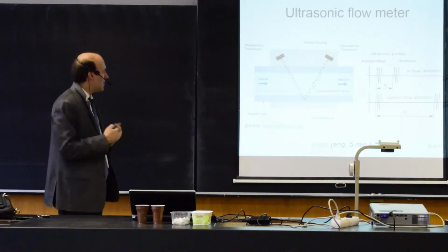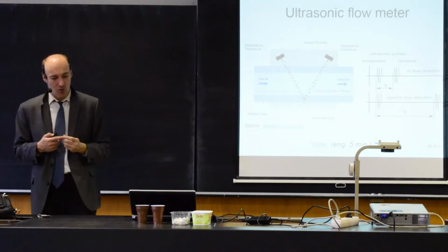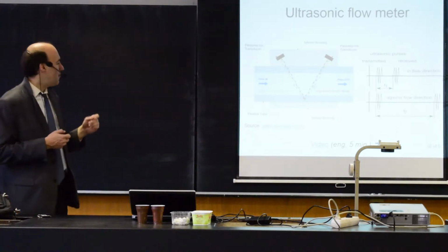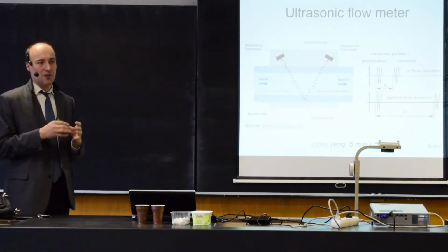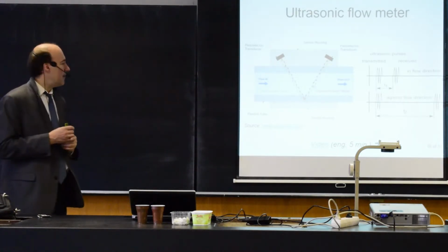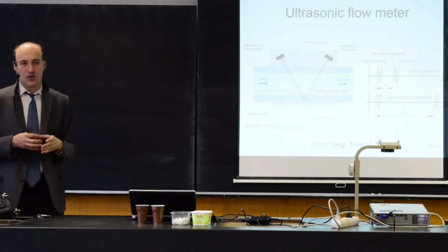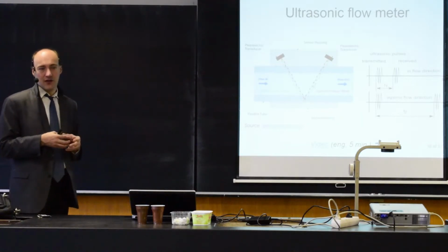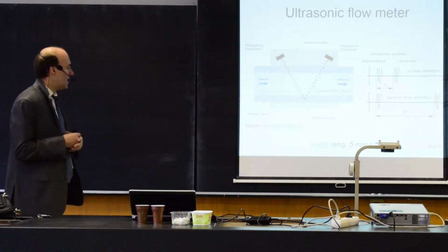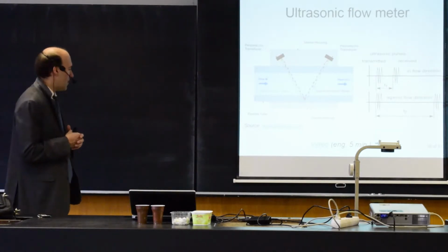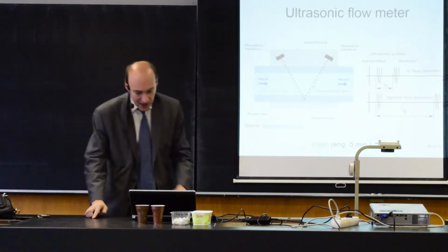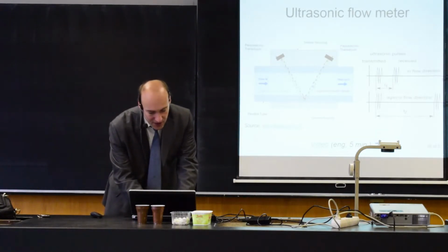So here we already see one disadvantage. The pipe needs to be completely full, because we multiply by the cross-section of the pipe, and if it's not filled, we cannot see the correct profile and correct flow rate. Let's take a look at the video again that explains this.